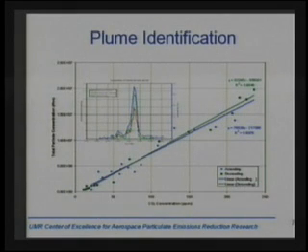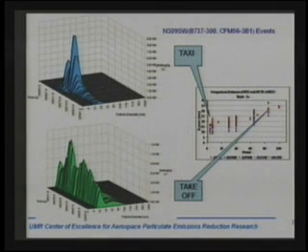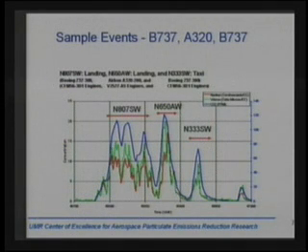This is looking at the particle count as a function of CO2 concentration, the kind of examples that I was showing you earlier. This is looking at the leading edge and the trailing edge separately, that in fact over that operating condition we had a similar engine operating point throughout that, and an equivalent emission index throughout. Phil already talked about this in some detail. In addition to what happens at the 50-meter probe, we're seeing the same kind of thing when we look at things way downstream, 200 meters or even further, where we see a bimodal distribution for the takeoff condition. A single modal, well, it's really bimodal, but the two modes are right on top of each other for the idle condition, because the small particles are dominating on top of the smaller soot particles that we'd expect at idle. And even for particle numbers, we can worry about overlapping plumes, similar to what I showed you earlier.